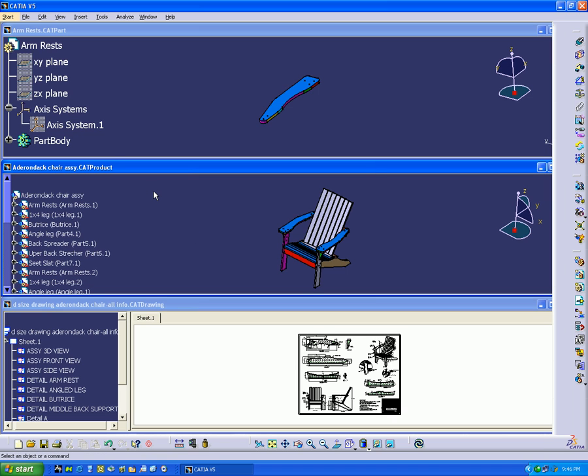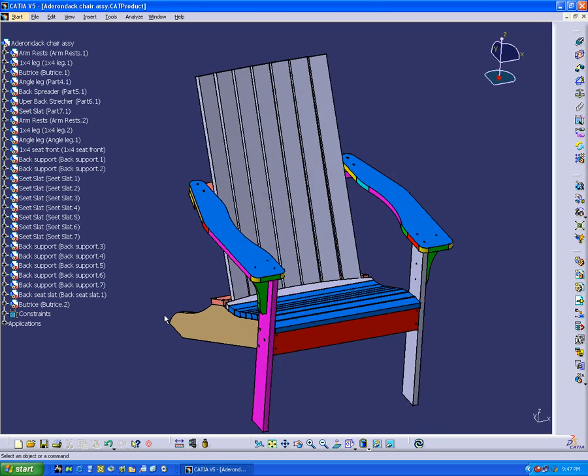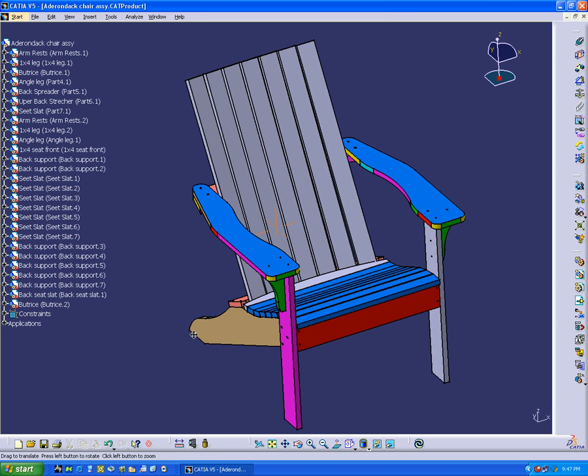Anyway, let's go into the .CATProduct, and I'll show you how that works. So I'll click on it, double click on the title bar since it's active, and we'll full screen that assembly file. So what we've got here is an assembly, which, like I said, is a .CATProduct. In the assembly file, we don't create geometry like we do in a part file.